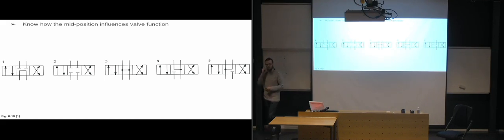One of the positive things with this is that if it's going to remain in this position for long stretches of time, so that for an example, every 15 minutes you're going to switch it over to one of the sides and keep it there for a couple of minutes, and then you're going to let it go back into the middle position, it means that the pump is not going to be running at full speed at all times. So the pump is having very little resistance. It's not getting any particular amounts of wear and tear either when it's running directly back to tank. So it's a very beneficial position for the pump when it's running constantly.